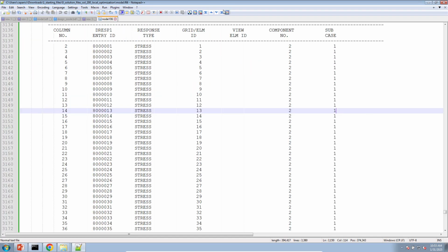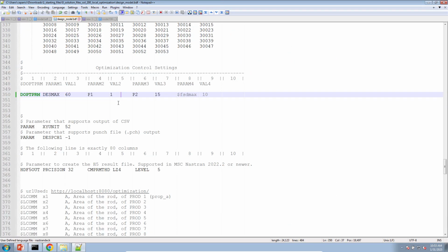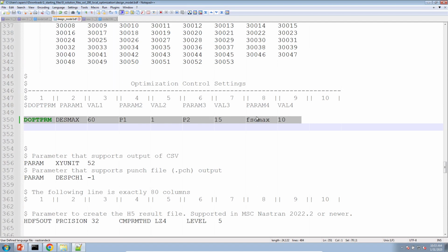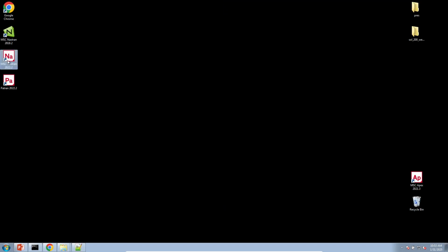Okay, my apologies for the confusion. So the cause of that problem was the following. I submitted an odd configuration here. What I had in this command, I have the fully stressed design option on, FSD max equals 10. That was causing the issue. So when you disable that, it allows the procedure to finish to completion. So let's go ahead and run that.